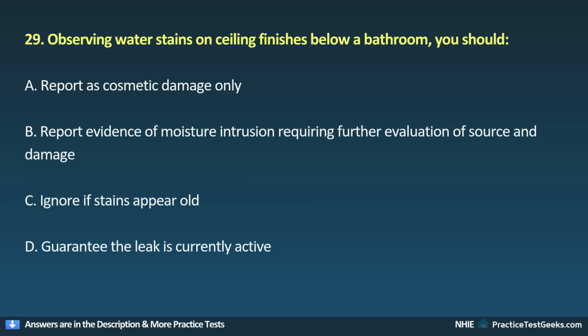29. Observing water stains on ceiling finishes below a bathroom, you should A. Report as cosmetic damage only. B. Report evidence of moisture intrusion requiring further evaluation of source and damage. C. Ignore if stains appear old. D. Guarantee the leak is currently active.